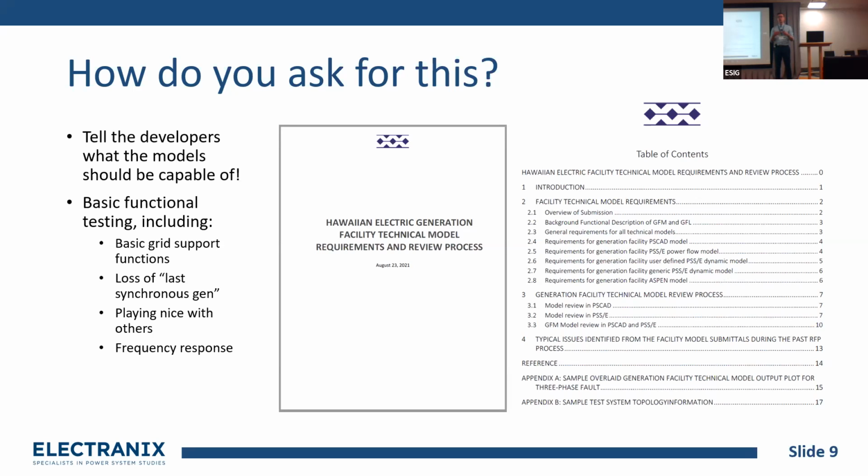We said we wanted, in fact, we didn't even define the functional behavior. We just said, here's a model of some tests we're going to do. We're going to, for example, put your converter in a system, and we're going to drop a synchronous condenser from it, the last one. So now it's just you and the load. Is it going to be stable? That's the test. We're going to put your inverter together with another inverter of the same type. Are they going to fight? If not, that's a pass. If they fight, that's a problem. Is it going to get us the frequency response that we want?